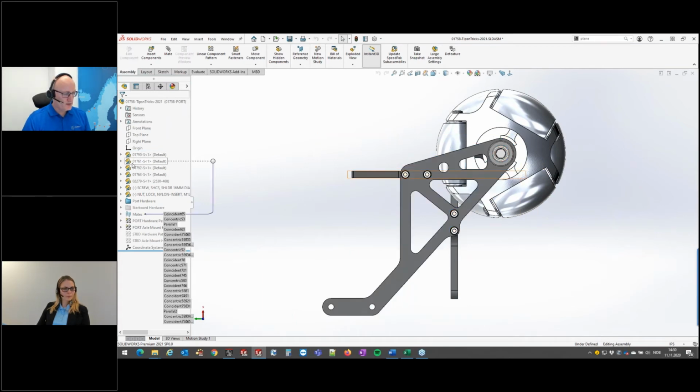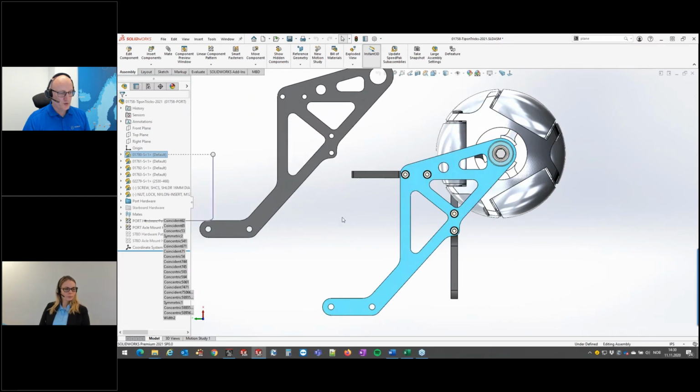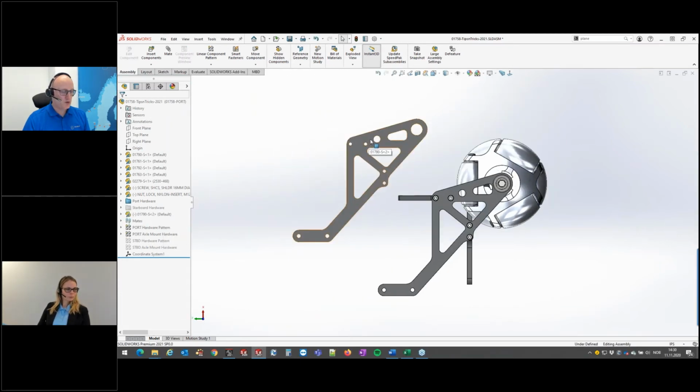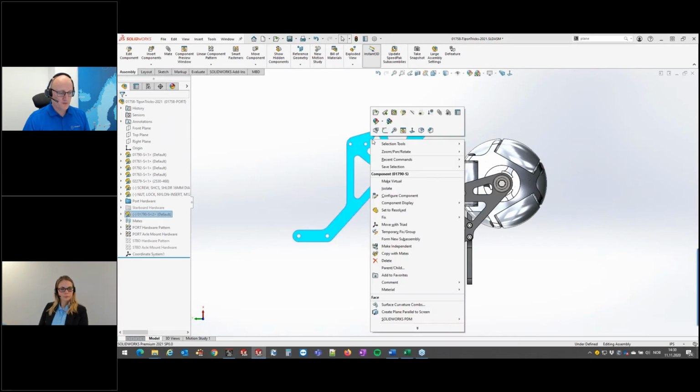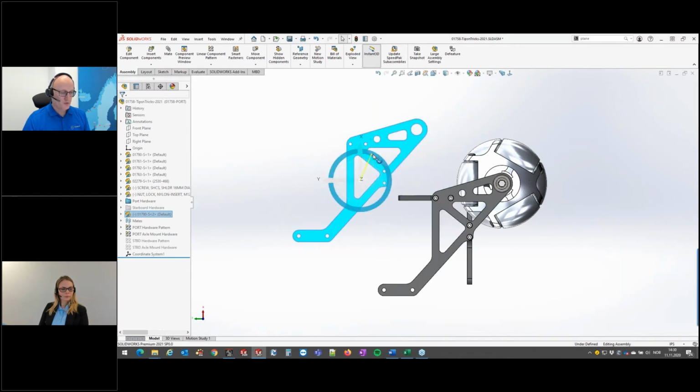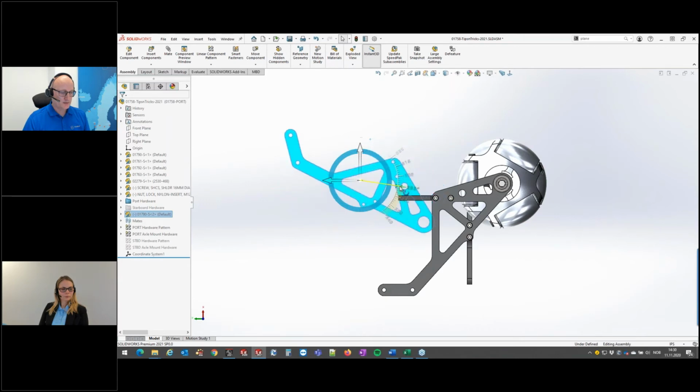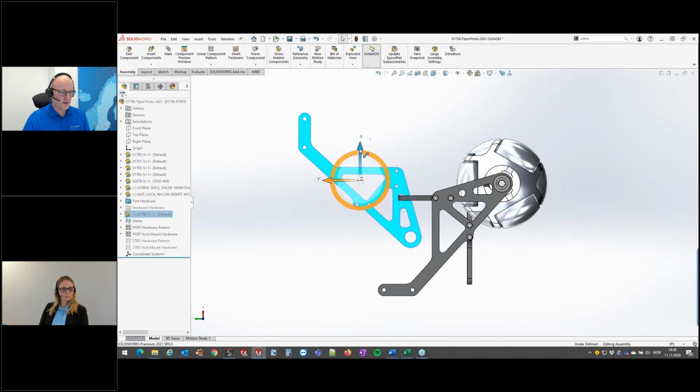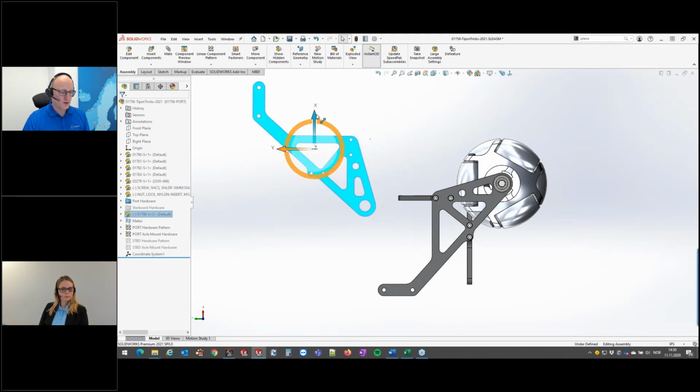Also, to orient the model, in some cases you might want to rotate or move the model in relation to something else in the file. And for this, you can use Move with Triad, and you can rotate the model like this. If you hover the mouse over these lines in this ruler, you can have it rotated in whole steps, and you can also pull the model along axis like this.